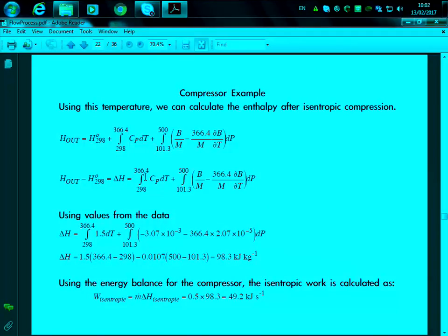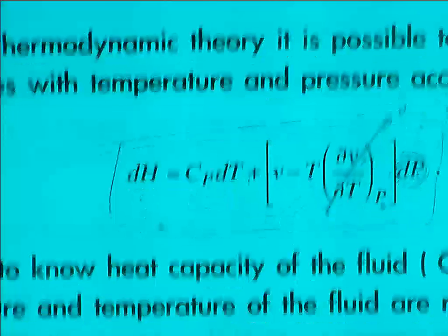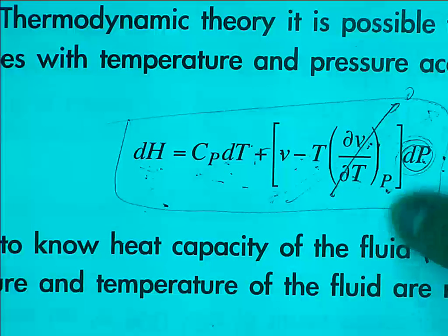So now we're going to obtain the changes in enthalpy under isentropic conditions, and for this we need to refer to the equation for delta enthalpy that we saw last time. So it's basically this equation, but without this one cross. That was for the example that we solved last time. Okay, so in here we have a negative value, and that's why it becomes negative here. So this comes from this equation. We solve it using the virial equation of state again. That was the approximation that we were asked to do. And we obtain the delta H.